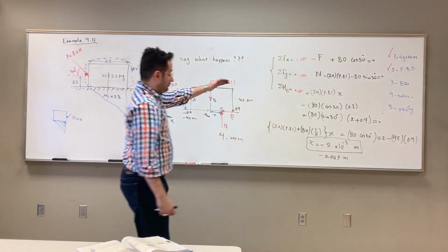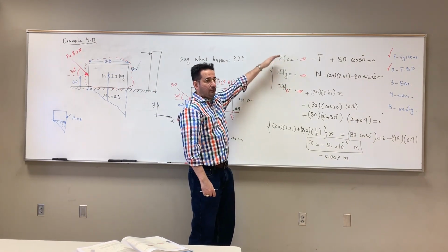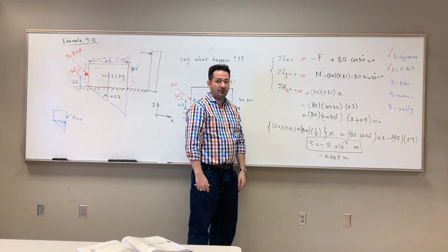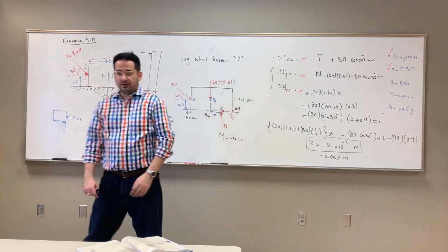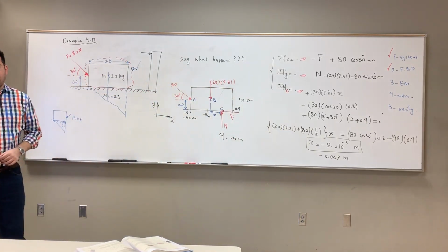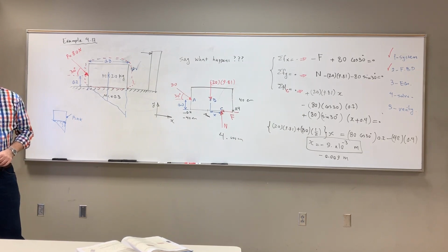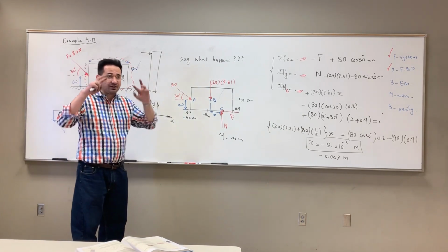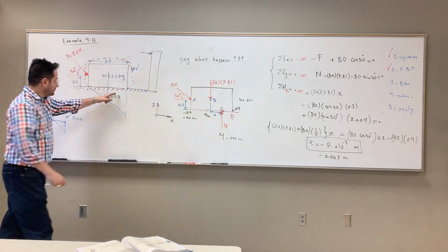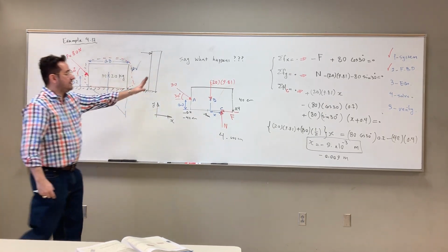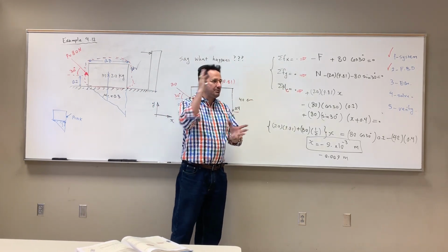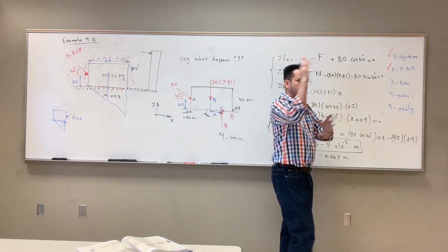This equation that I use, they're just enough to explain the phenomenon of equilibrium. So if the x was inside that rectangle right there, it would not move over. Yeah, in the range. But if x is outside that, that means the assumption we made for this geometric center is invalid. That means these equations are invalid. That means that this thing is a dynamic motion, it's not equilibrium. That means it's tipping over.